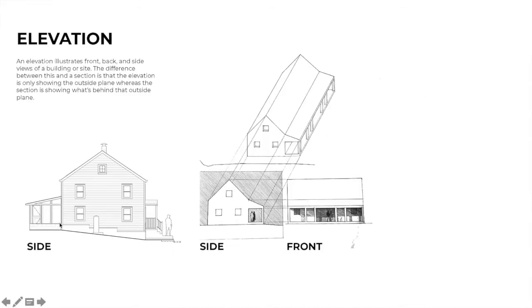Elevations are projected drawings, everything at a representative length to the scale of the drawing, looking straight at it. There's no perspective distortion present here. So objects or spaces or constructs that project off of this house are not vanishing whatsoever. So we can understand the scale of this porch and this solarium. Where I come from, we call these Michigan rooms. They are represented all at scale to one another, with no perspective distortion whatsoever.